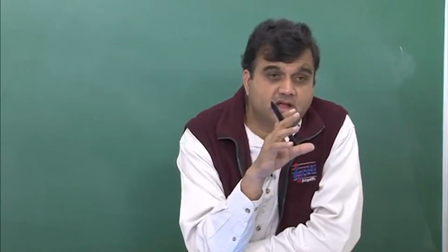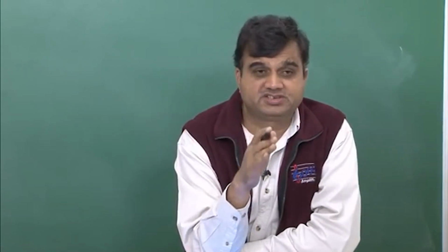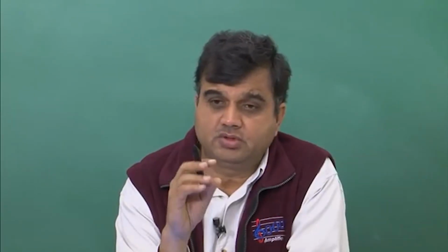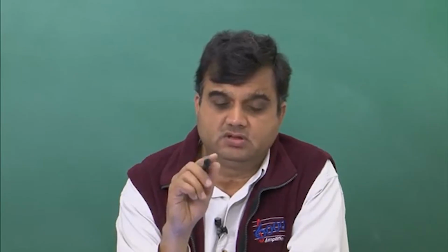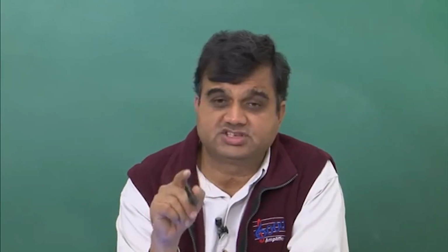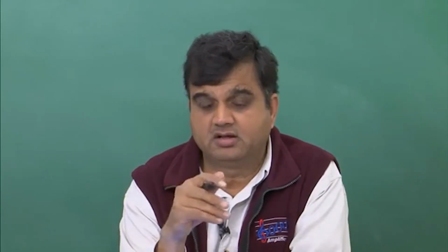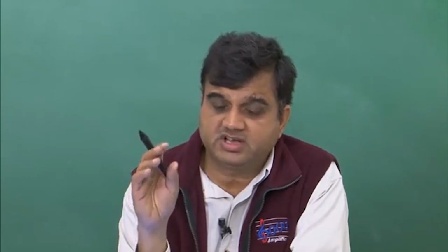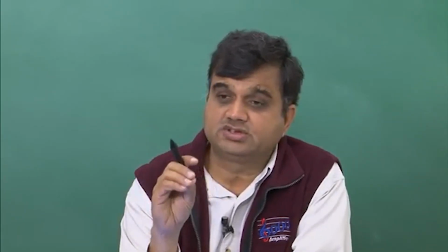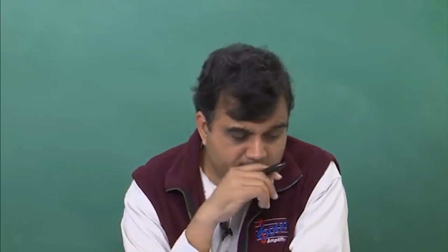So, the aim of today's lecture is this: once we have generated values of xk, we have already figured out how to compute specific amplitudes of frequencies associated with each xk. The way we do it is we multiply each xk by 2 and divide it by the total number of points, capital N, and that is the specific amplitude corresponding to each xk. Now, each xk is also associated with a specific frequency. That is what we will learn how to figure out.